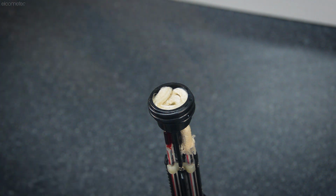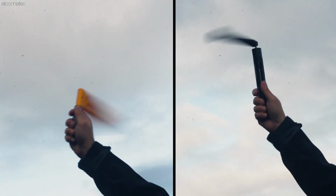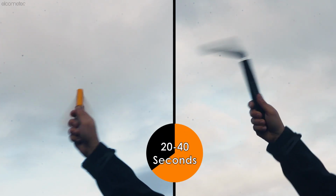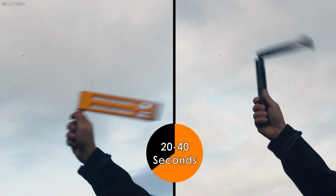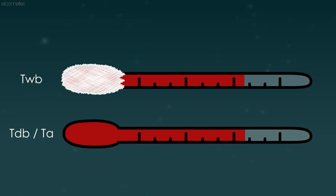Once the wick is fully saturated with distilled water, you then whirl, or spin around, the hygrometer above your head for between 20 to 40 seconds, at an approximate speed of 3 revolutions per second or 180 revolutions per minute. As the hygrometer whirls through the air, the water on the fabric evaporates, cooling the thermometer bulb, working in the same way perspiration cools the skin when it evaporates, like in the example from before.